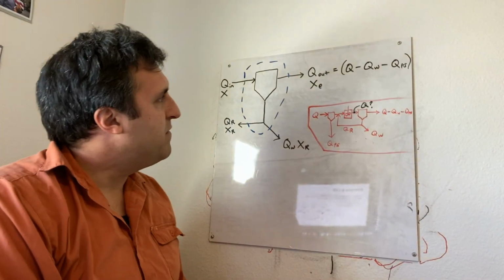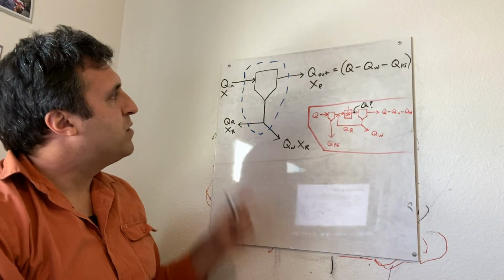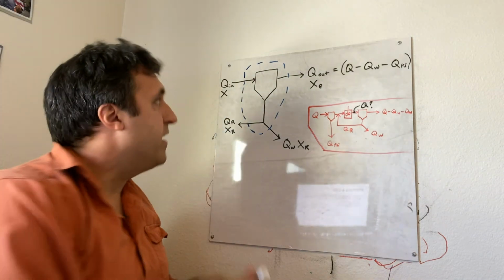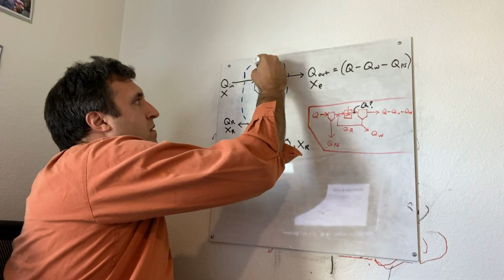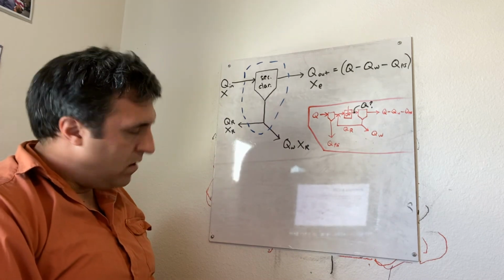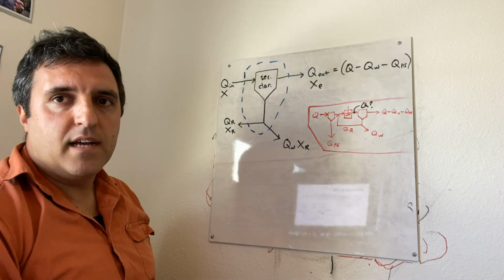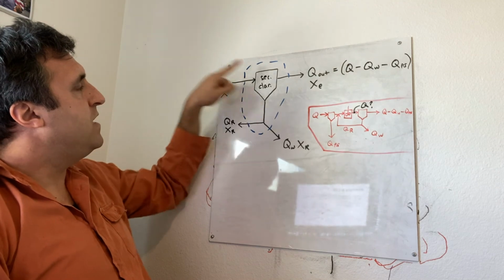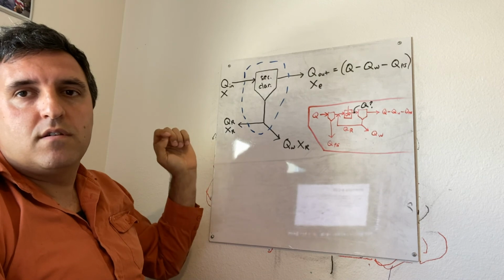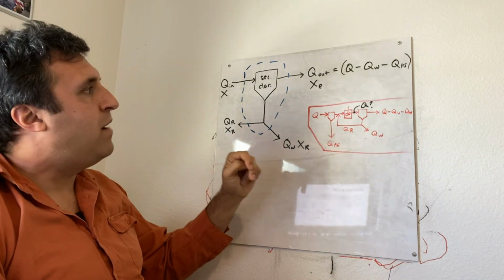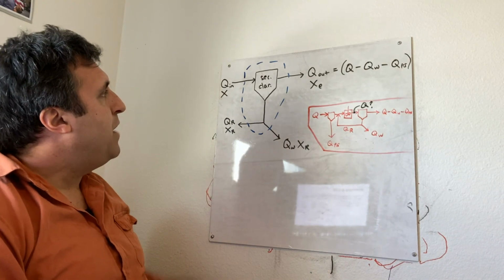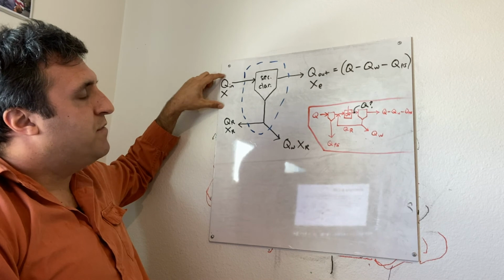All right, so in this problem, we have the same system as the last time. However, we're drawing our mass balance differently, right? Because we're only looking at the secondary clarifier here. All right, so otherwise, the same approach applies. We're still using mass balance. We have our boundary. The general mass balance formula: accumulation equals mass flow in minus mass flow out plus growth. That still applies. However, what's coming into our system is different than last time.